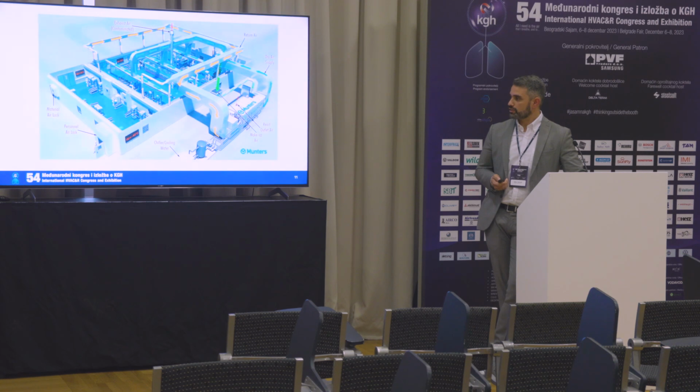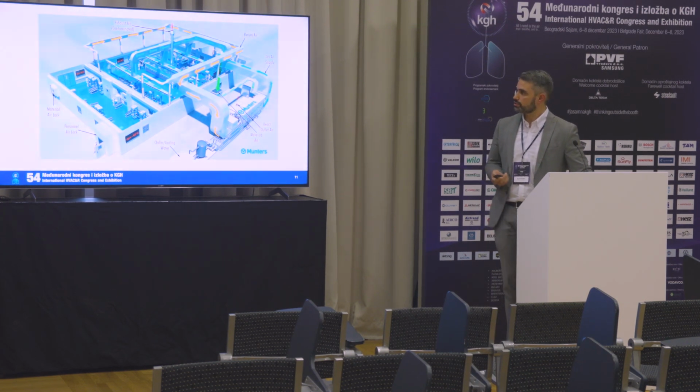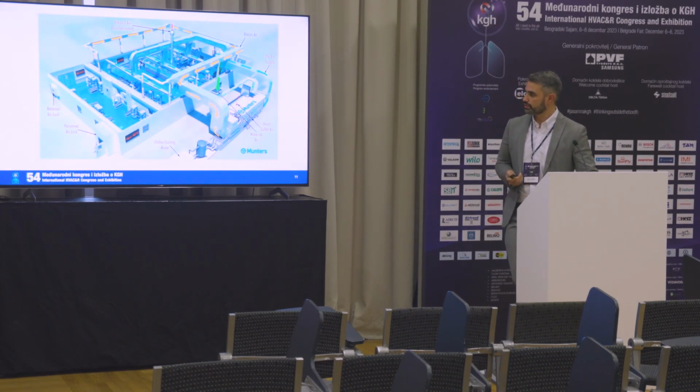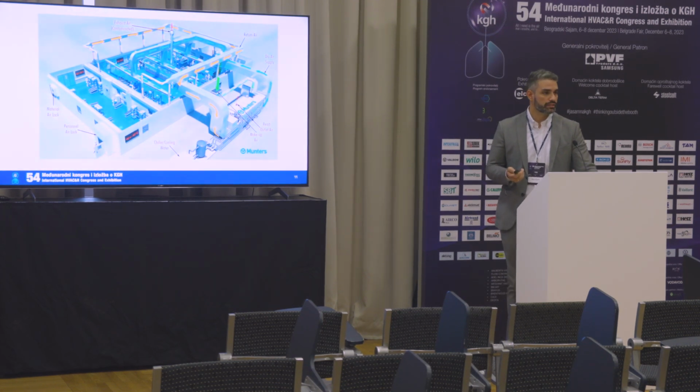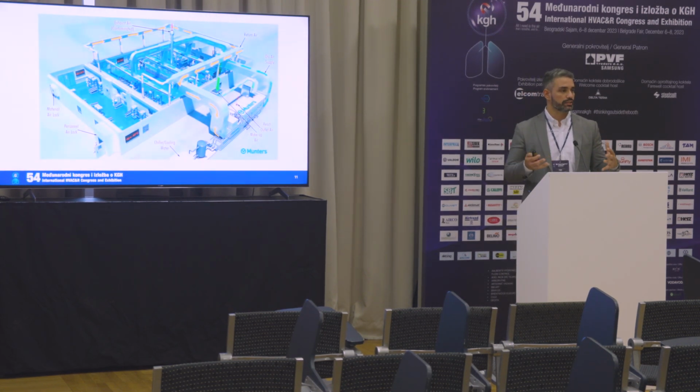A typical clean dry room setup has material airlocks and people airlocks, which prevent infiltration from the outside, from the next, let's say, part of the facility. And this facility, as you see, has a pre-cooling coil, and as mentioned, fresh air, return air, supply air, exhaust air, and also overpressure counted in. An envelope is built in such a fashion that it is almost a completely sealed room.